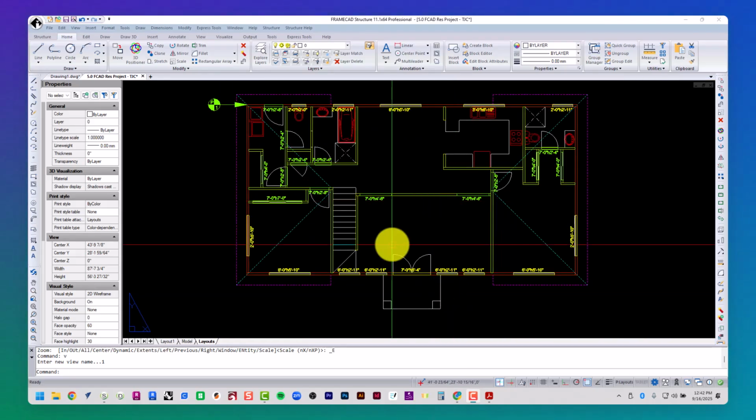Integrity checks highlight any drafting mistakes we may have made, such as walls exceeding the maximum length that we had set earlier in the project. This command is your best friend in eliminating errors and creating a functional design. It's recommended that you run an integrity check several times on each job. The settings for integrity check can be found in the panel setup dialog box.